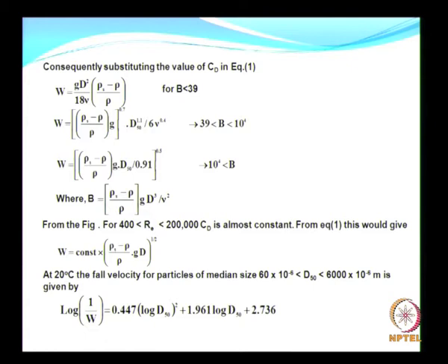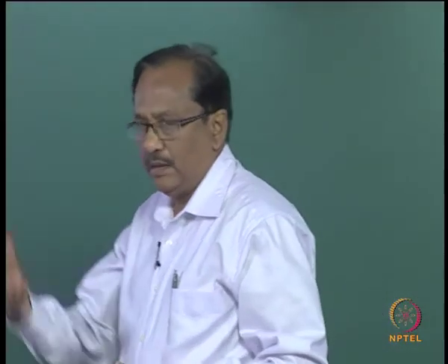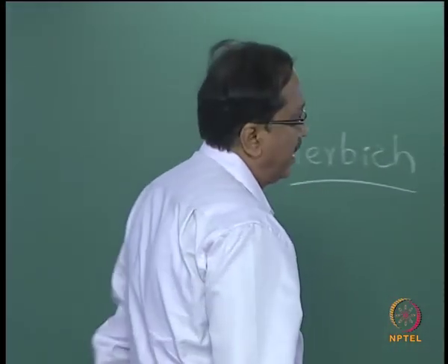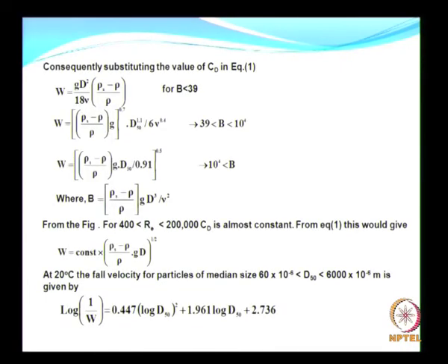So the fundamental thing is equating the two forces: one is the drag force that is going to be exerted, and the other is the weight with which the whole thing is coming down. When we equate this, you get what is called the fall velocity, but we have a clear distinction, or this variation is going to depend on the value of this parameter.